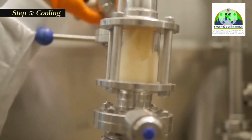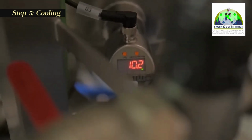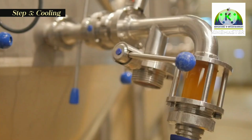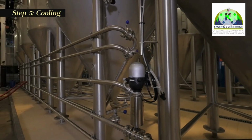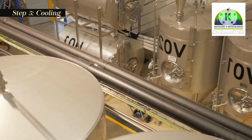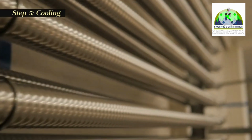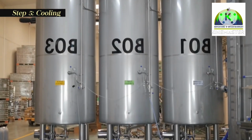Depending on the beer style, the wort cools quickly to 7 to 35 degrees Celsius as it passes through the heat exchanger. The working principle of the heat exchanger is that cold water or glycol passes through the cold water side of the heat exchanger, and the wort enters from the hot water inlet on the other side, and then the cold water or glycol will take away the heat in the wort. Although cold water or glycol cooled the wort, they did not touch it.